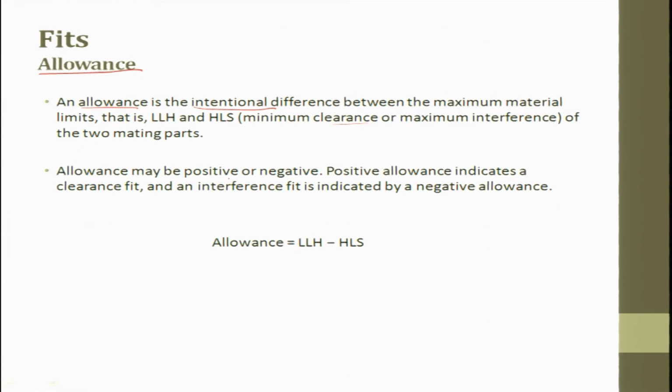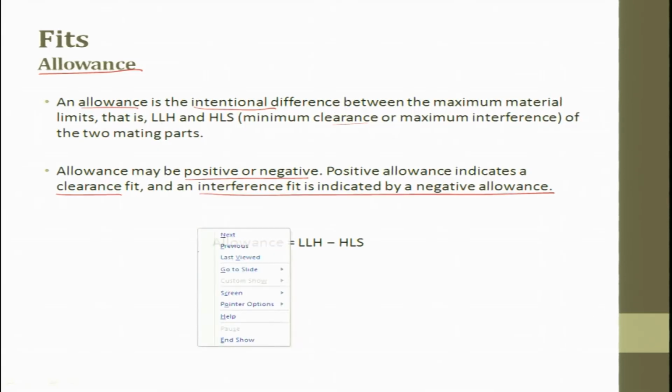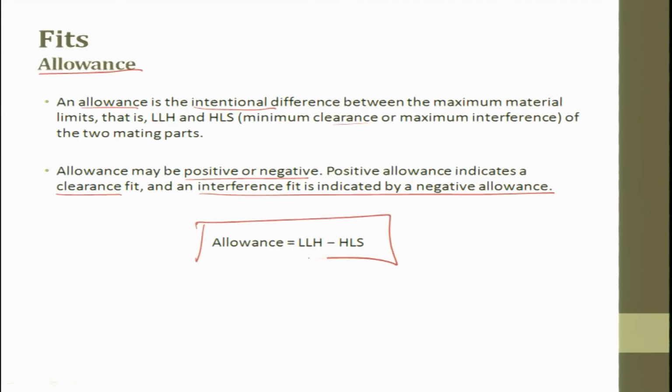Allowance may be positive or negative. Please make a note: allowance need not be positive alone, allowance can also be negative. Positive allowance indicates a clearance fit and negative allowance indicates an interference fit. This formula is very important. So in the examination, there can be a problem asked on this topic.